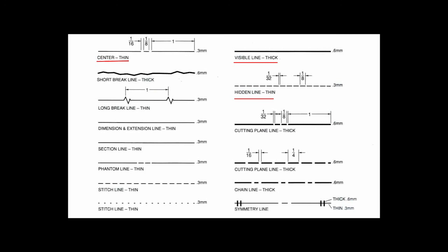The lines that are indicated as thick are generally drawn with a harder hand with a darker shade of pencil, and the thinner lines are generally drawn much more lightly. You can either use different types of pencil leads to draw these lines, but I got through my course using the same pencil and varying the pressure I applied onto the paper. Whatever works best for you.